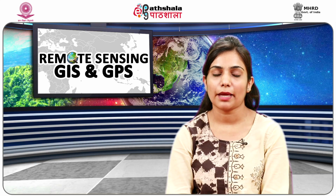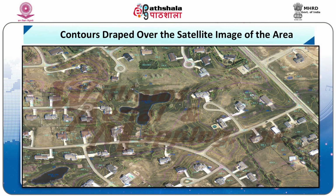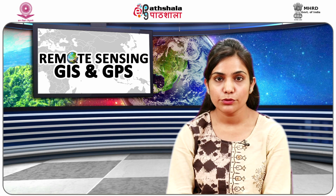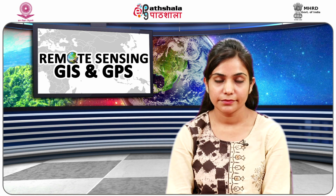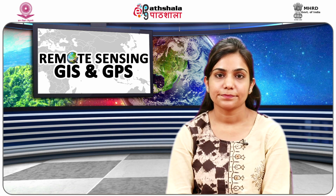Next application is topographic mapping. One of the most widespread uses of photogrammetry is topographical mapping, which is considered the primary approach to GIS based data collection and updating. It provides topographical information of the area, and figure 12 shows the contours with the topography of the area. Next application is terrain models. It includes digital elevation models, digital terrain models, spot heights, contours and break lines, which in turn are useful to superimpose over an orthophoto, useful to determine irrigation requirements and drainage requirements, and ideal for rural property mapping.